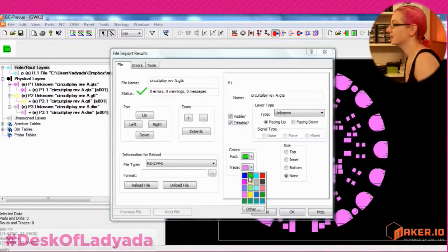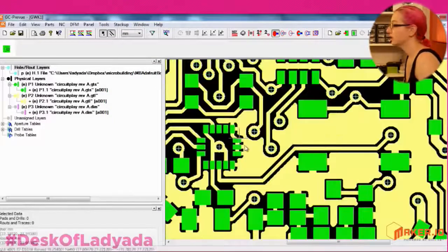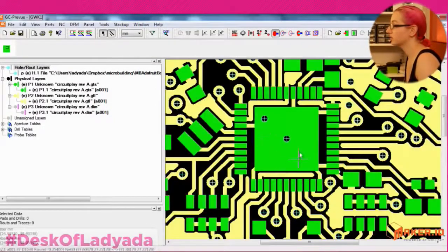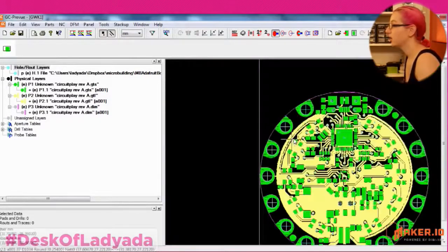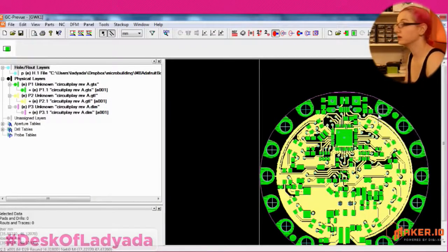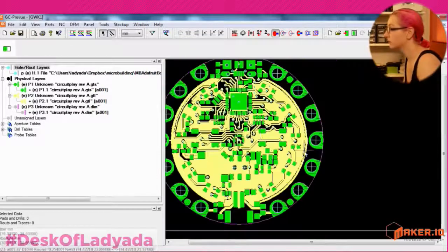So next up, let's do the stop layer. Another good thing to check, make sure that you have a stop layer, for example for ground plane, for center ground pads, make sure you have a stop there. All of the pads around here, if you're making custom components, make sure that you have a stop layer. And then they'll look good. The pads look nice and square.